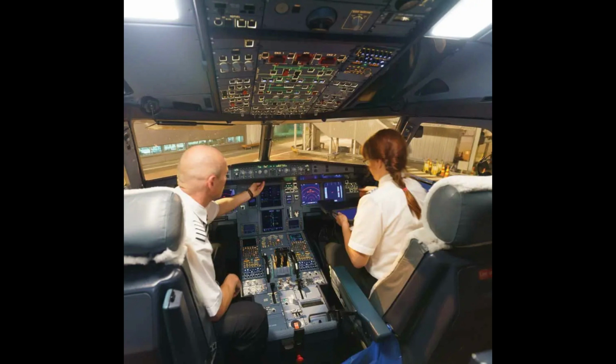How to use an autopilot function. The following steps are required to use an autopilot function. 1. Specify desired track as defined by heading, course, series of waypoints, altitude, airspeed, and/or vertical speed. 2. Engage the desired autopilot functions and verify that, in fact, the selected modes are engaged by monitoring the annunciator panel.